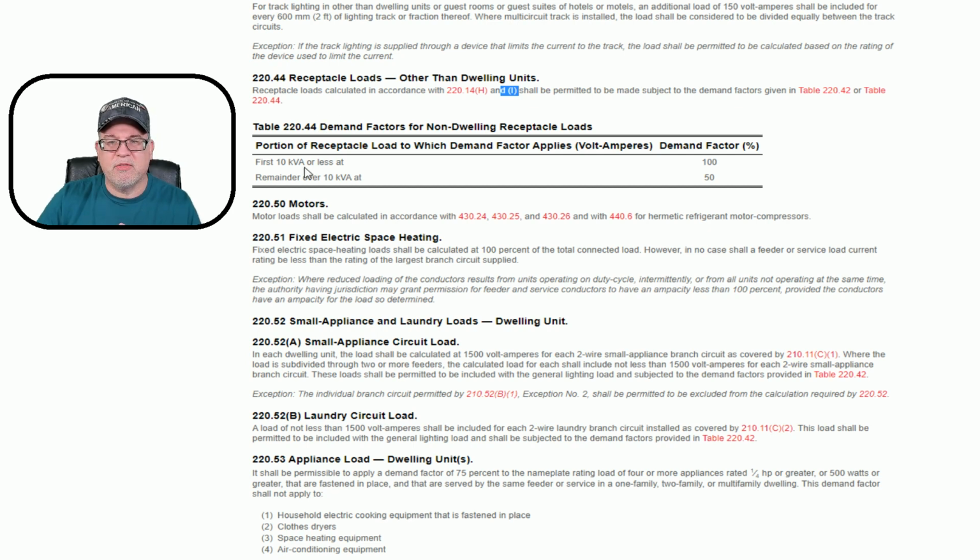And so in this case, the first 10,000 of the value that we just worked up is taken at 100%. And then whatever the remainder is over that 10,000, it's at 50%. That's huge, and this is something that you find on exams. You have that first step that we did to totally get our connected loads, but then you have demand factors that are permitted to be applied.